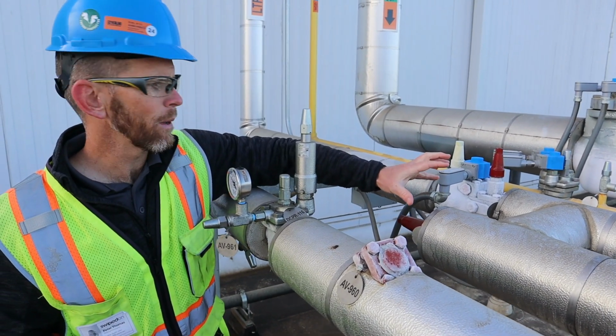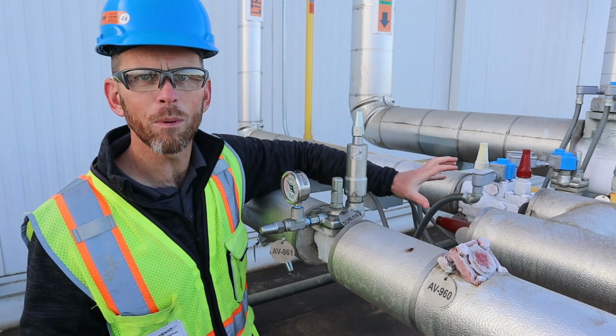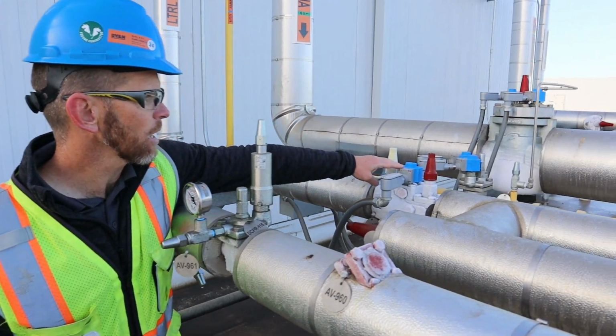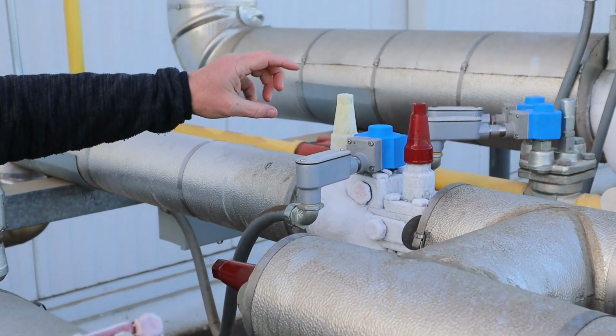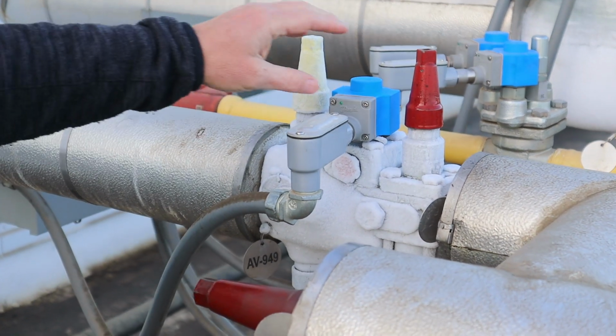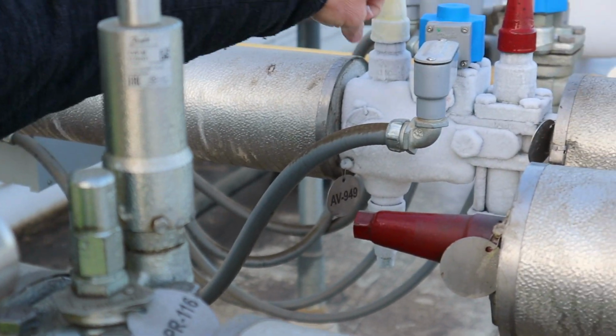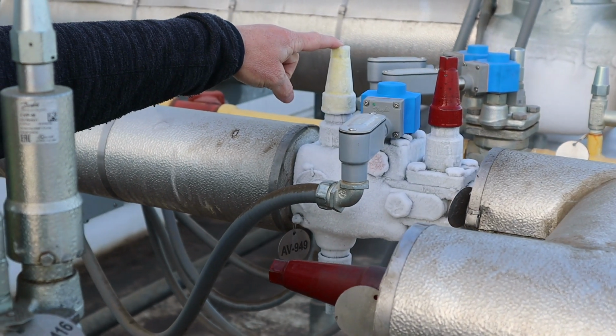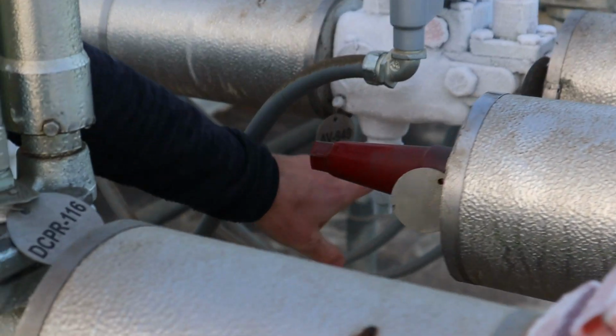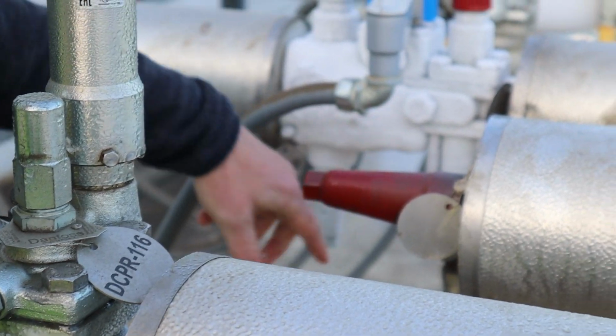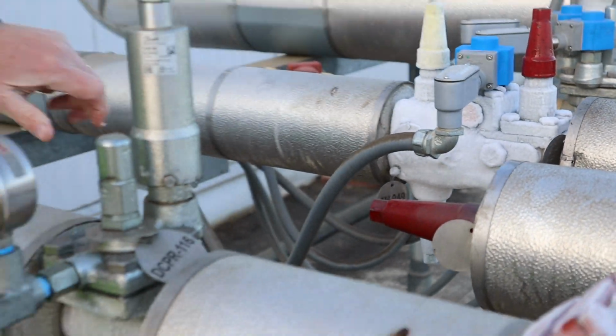That adds a little bit of complexity, but only one of those is open at any given time. This is the liquid valve group, and this is a block valve, so we've got all of this contained within a single block. We have an isolation valve, a strainer, a solenoid, a hand expansion valve, that's the yellow handle, and another isolation valve. There's also a check valve component within this as well. It's frosted over, so it's kind of difficult to see.